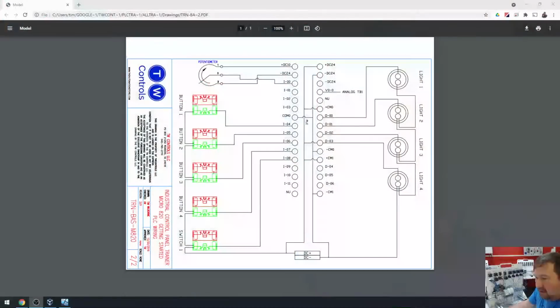Now, absolutely the most left out piece when wiring your inputs is this COM0 right here. It doesn't really show up as maybe necessary when you're starting out, but this is what is going to complete your circuit. And so we always want to ask ourselves, do I have current? So I'm sending plus 24 volt to a button, and I'm coming back to input 4, but I have to complete the circuit to this minus DC right here.